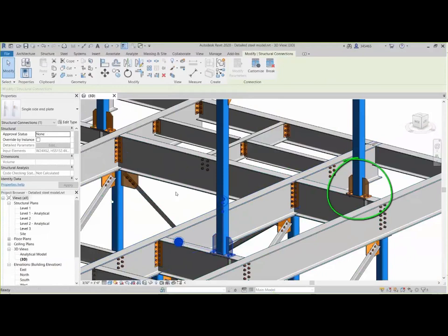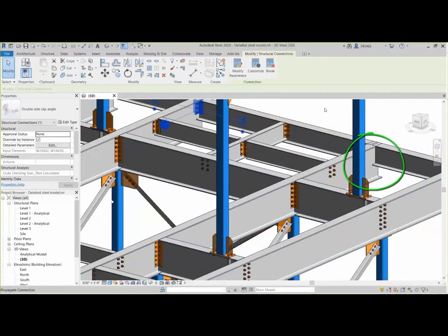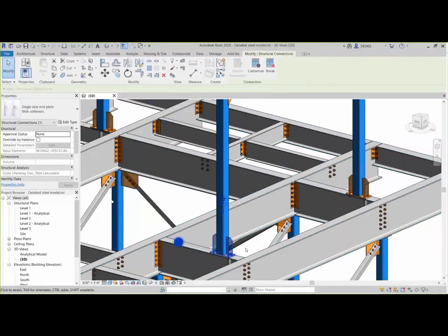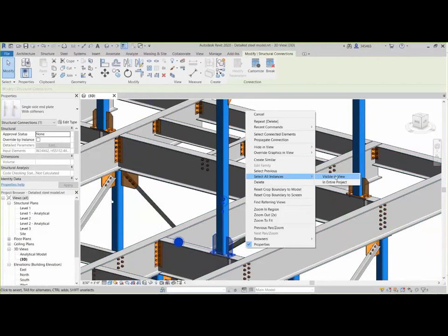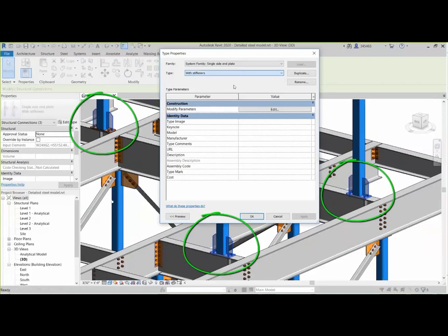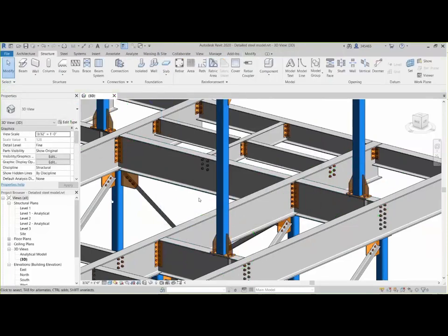And in typical Revit fashion, if I need to change an instance of that, that's simple by grabbing that instance, right-clicking it, grabbing all the existing ones in this viewing case, and then swapping those out. And so think about how long it took us to really do that. And you can see in just a matter of minutes, we've got all of our connections happening. So we've just saved a tremendous amount of time going there.